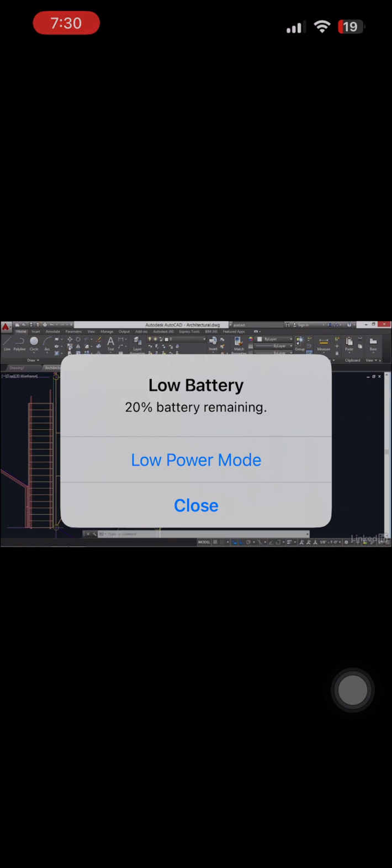Let's try that again. Copy this chair. So I've clicked it. I'll right click to exit from the select objects mode. Now I'll specify some arbitrary base point. I'll move over to the right and click. That would be the second point. Notice, however, that the copy command keeps going. That allows me to make multiple copies. I could then click another second point, and so on. I could turn off ortho by pressing F8 and make copies all over the place. I'll press enter. Now let's say I want to make a series of chairs that are spaced equally.